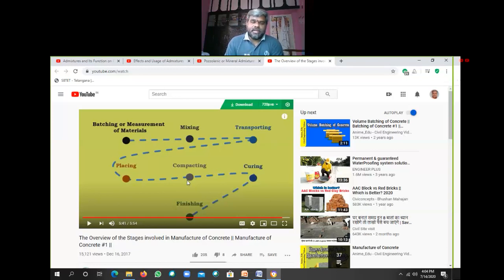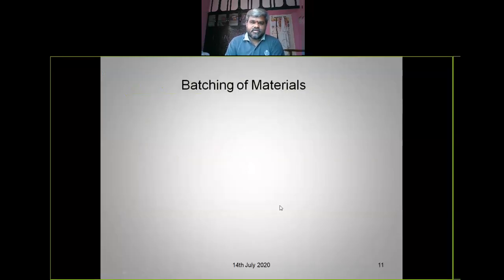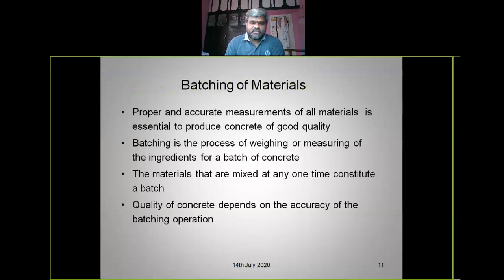The degree of compaction leads to the strength of the concrete, and the compressive strength of the concrete. Then curing is very, very important, as the hydration process is going on inside the concrete. Then finishing it. These are the stages of concreting. And what is batching of materials?